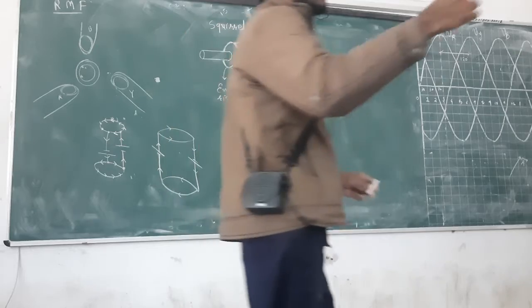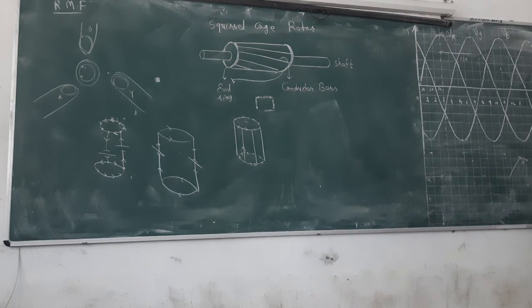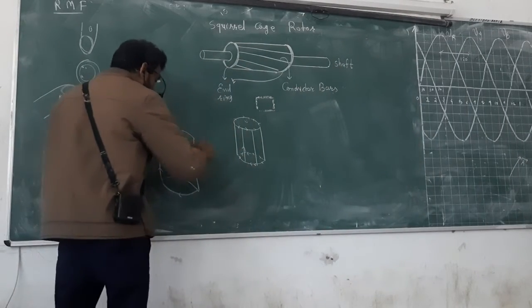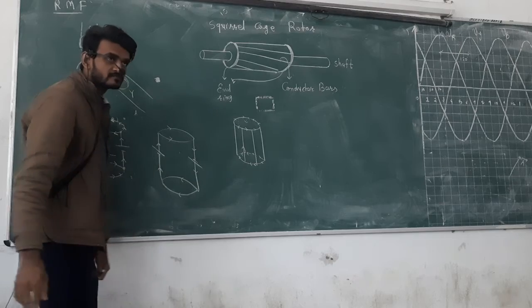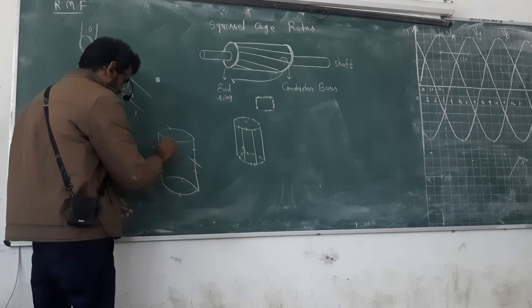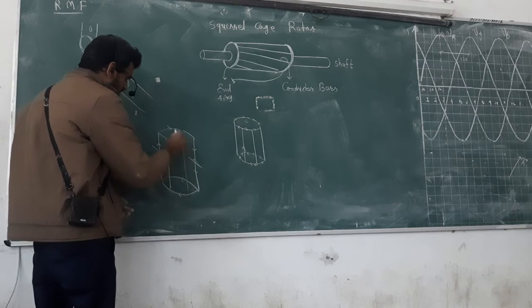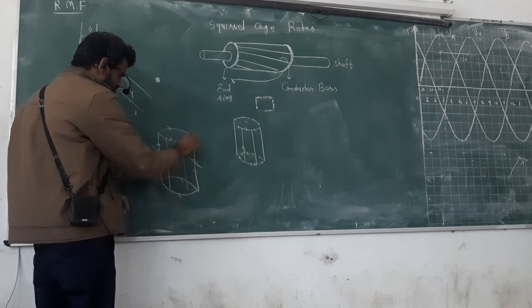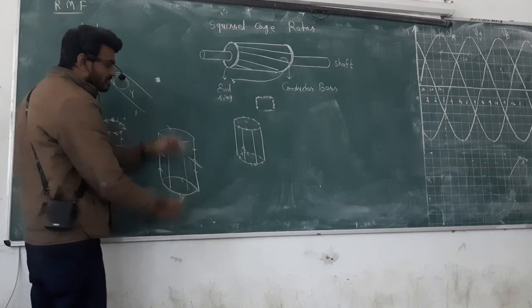This is the 20% portion of the induction motor, to understand how it rotates. So up to now it is clear: a rotating magnetic field is there, voltage is induced in the rotor, and the rotor conductors are closed circuit by clamping of the end rings. Even if extra conductors are there, here and there, all the conductors are short circuited by the end ring.